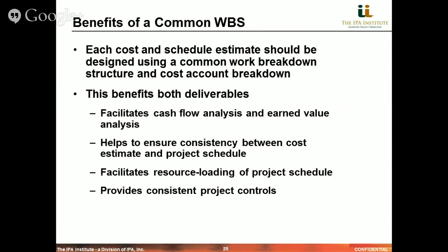Generally, your cost estimate is where your hours are loaded. You understand your crews and your labor expectations and productivity in your cost estimate. And by having a well-developed WBS that forms the framework for the estimate and the schedule, it becomes much more transparent to then resource load the schedule to ensure that your schedule expectations will not require a higher level or a larger peak of resources than will be available or than your system can withstand, whether it's by space or availability.